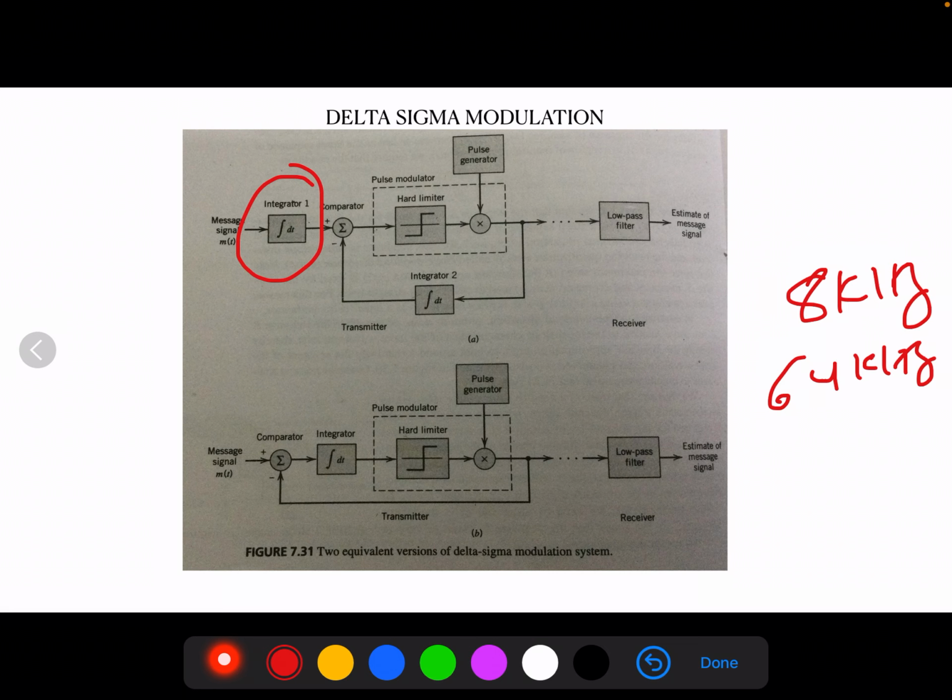Typical oversampling rates of delta modulation range from 16 to 32 kHz depending on the desired voice quality. So, delta modulation may provide a net bandwidth saving of say around 50 to 75% over PCM at the expense of more complicated implementation.